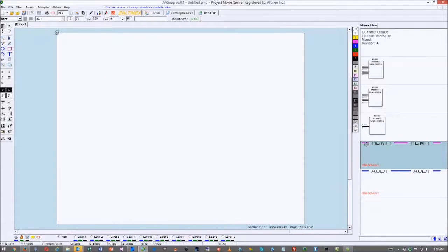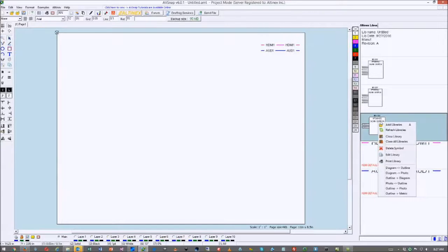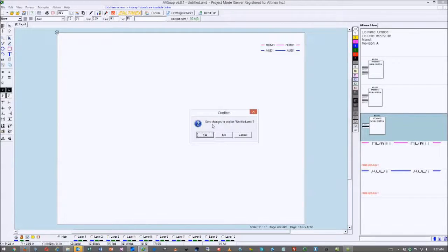So what I do, I can create a table of references, and I can just put them next to each other. So anybody who's looking at the drawing, they know what the audio cable is, what the HDMI cable is. I do the same thing with rectangles. I do the same thing with any object that I need to put on the page, pre-formatted and ready to go. All right. The next symbol that we need to talk about, let's go ahead and edit library.